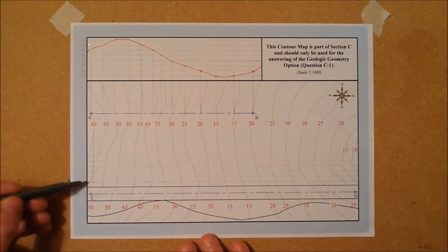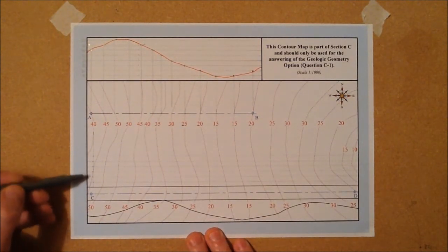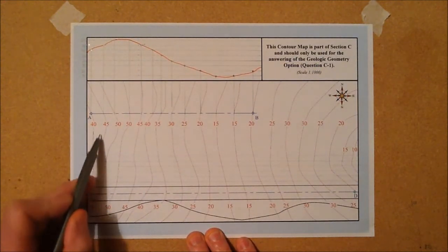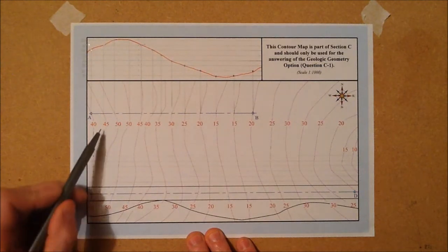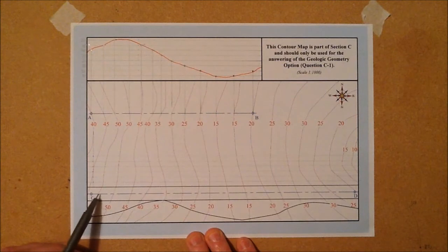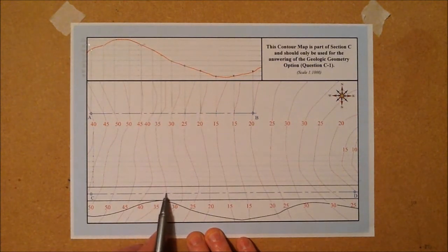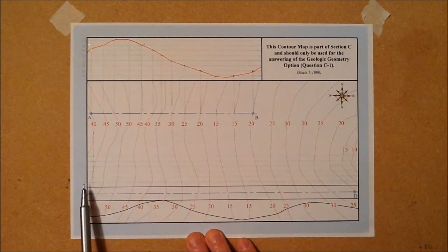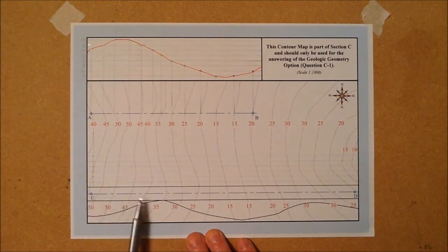So once I have my parallel lines in here, I'm going to mark in the corresponding altitudes. We see here at this point here, if you follow the contour out, this contour line is at an altitude of 45 metres. Okay, we know the road itself is at an altitude of 35 metres, which is at this height here, this contour. So therefore this means that the land around the road between this point here over towards our left, the land itself is actually higher than the road, so we know we're going to be cutting into it in order to create the road surface.